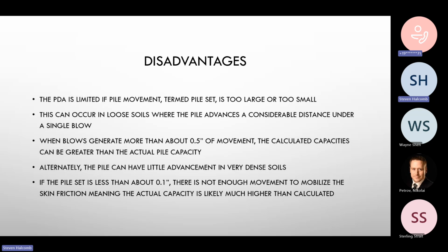Do you have any guidance on the blow counts, the range, what was it, 30 to 80? 30 to 120. Okay, that's the normal operating range of a hammer. Yeah, so when you're into the teens and 20s on your blow counts, it can be a little bit difficult in the field. And then definitely when you hit 100, there's just no movement in the pile. The contractor doesn't like it when their hammers are operating above 120 blows a foot because they're just working really hard. And that's what we define as difficult driving conditions.